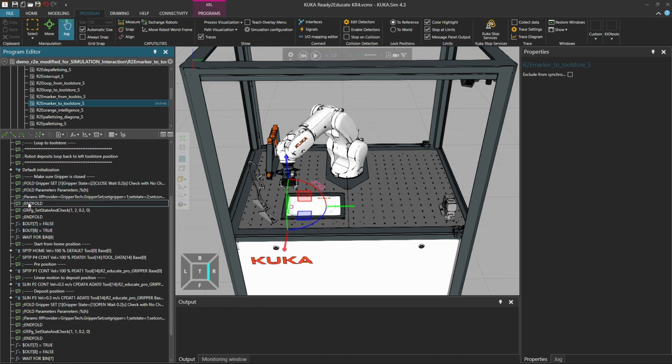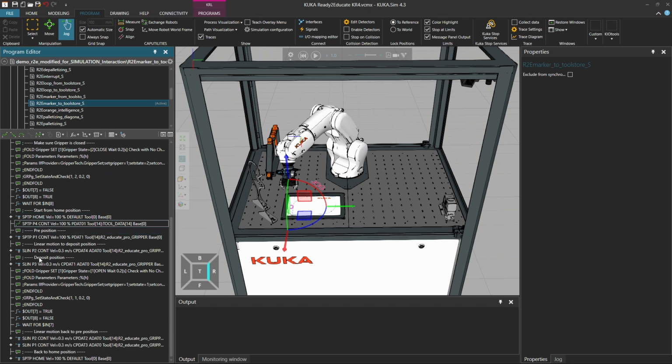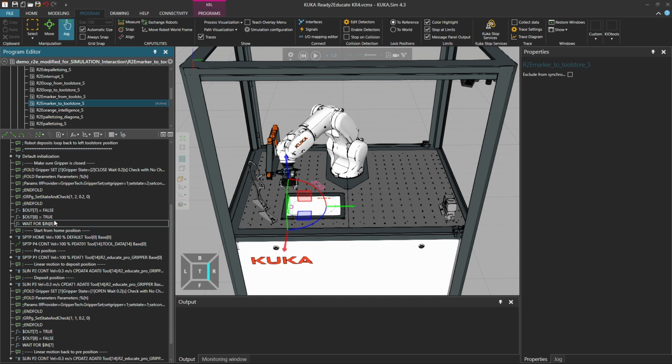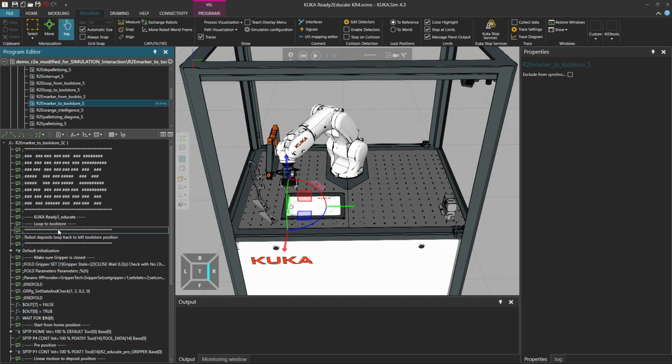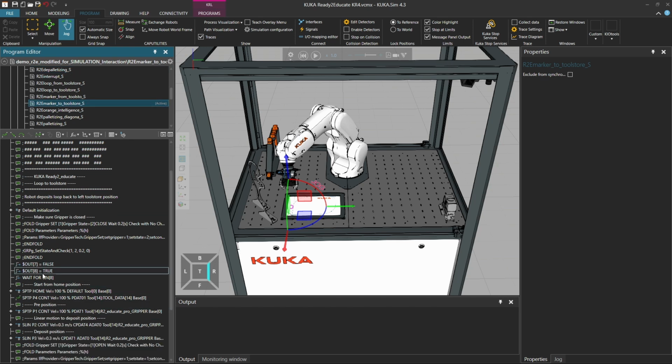These were commented out, and instead we use different signals. So at the moment, if we program as it would be on a real controller, then KUKA.Sim won't understand the gripper tech topics here, and thus we have to use the ones with _S in this case, with the outputs that we normally use.